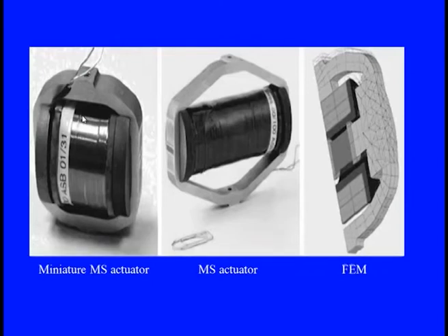So as you can see on the screen, we have the miniature MS actuator, and these actuators come in any of the forms according to the applications where field and load applications are required. And then it can be solved using the finite element method, and can also be mathematically formulated. The experimentation can be done using these magnetostrictive or electrostrictive material layers in a composite, and then can be performed to see how much vibration suppression there is or how much actuation can be obtained from these parts.